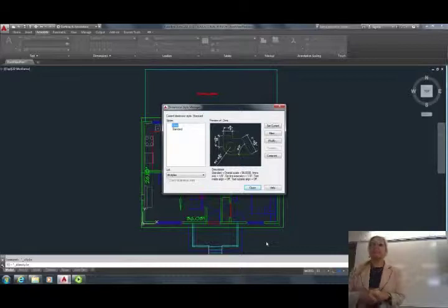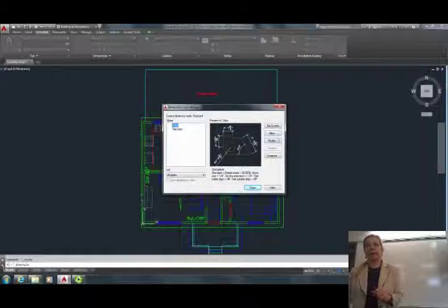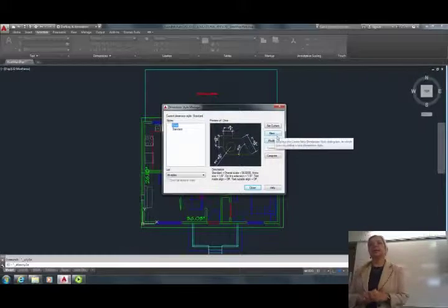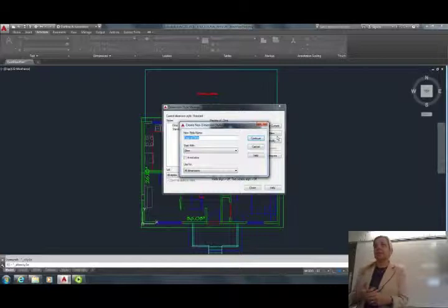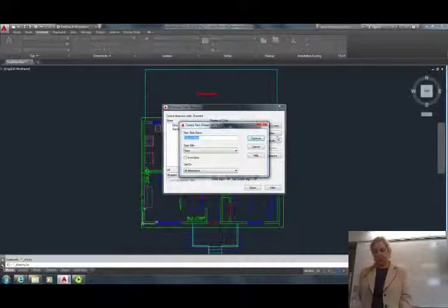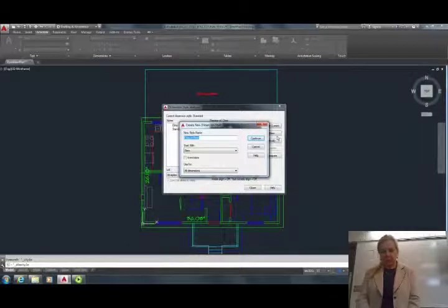Now you're here in lab. I will be checking this. So when you give me your final project, I will go to dimension settings, and I will look that you've created your own new style. Okay? But I've highlighted dims because what I'm going to do is take the style that's a little bit better than standard, that's used basically by mechanical people. I'm going to override it. I'm going to call it my dims green project.